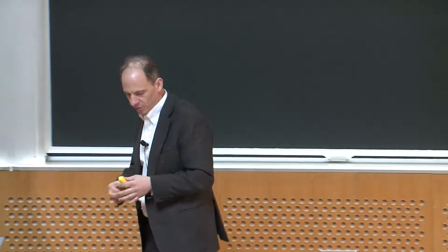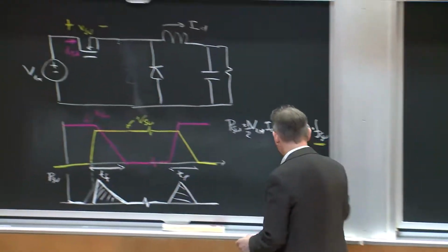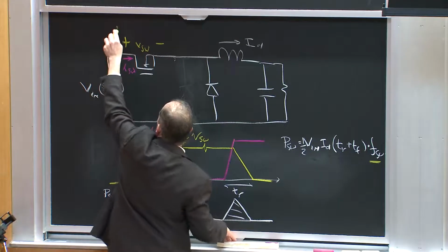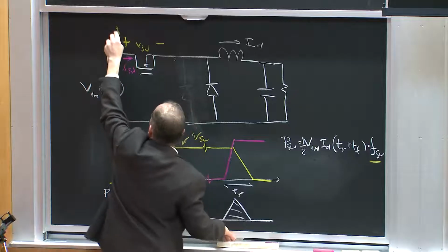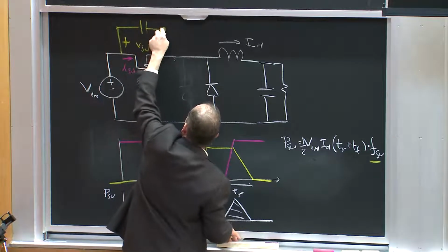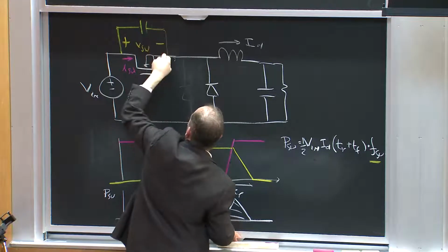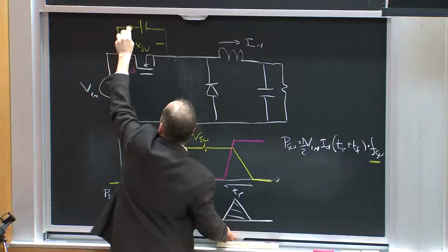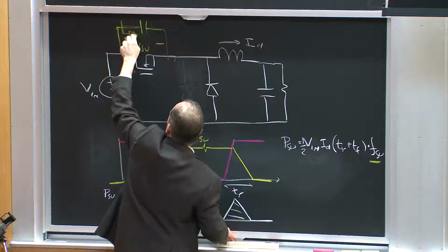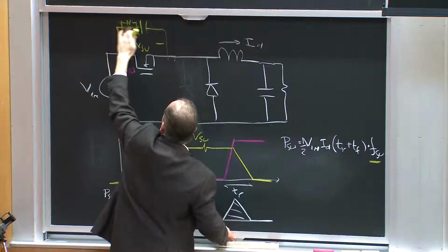And one of the tricks that we showed earlier in the term was, okay, if I put essentially a circuit that looked like this, a capacitor across the device, ideally, but what I will do is make it so that instead of putting it directly across the device, in the forward direction it looks directly across the device, and in the reverse direction, I have a resistor here, okay?